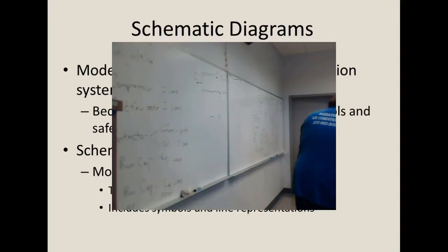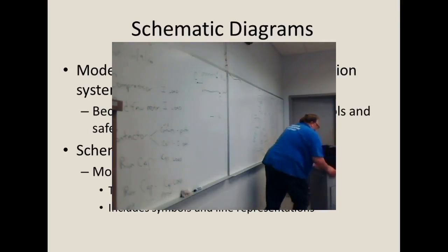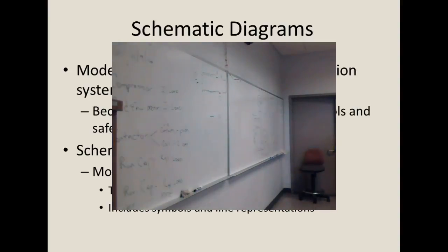Now, whenever you start ohming something, y'all, you always want to touch the leads together, to make sure your ohm meter works. And his is 0 now. Now, you're going to go from the bottom left to top left. I'm going to get another compressor.